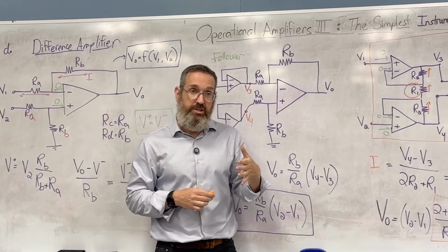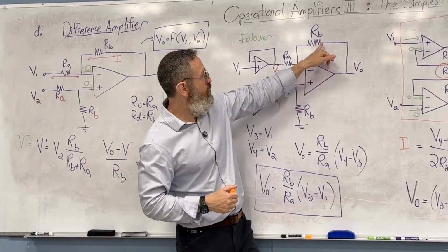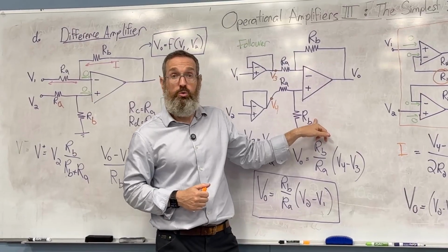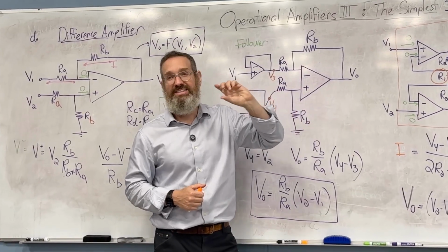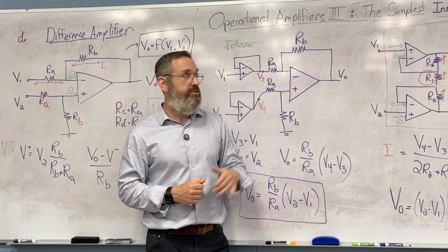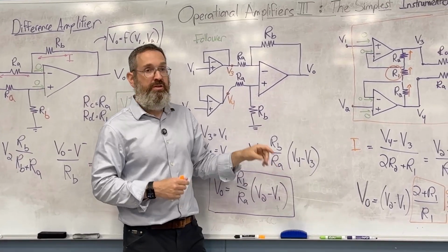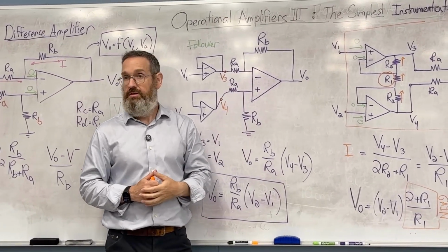For some applications, within a fraction of a percentage. So you may say, I found a 2 ohm and a 2.01 ohm. Is that good enough? That's not good enough. Go back to the bin. Right? So you're spending a lot of time not just finding the resistors you want for the gain, but making sure you can balance them perfectly.